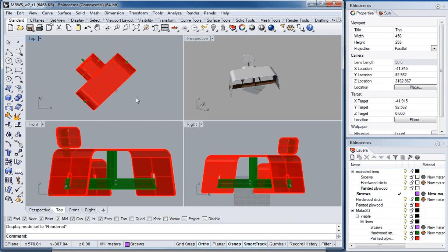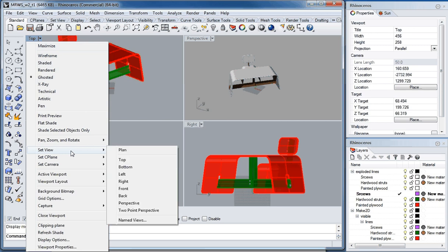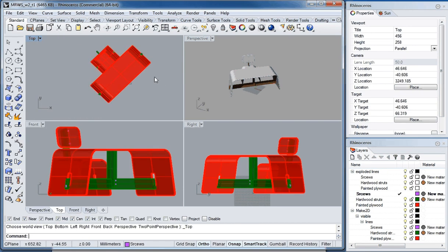So we'll just do that in here. Now what I'm doing here is I'm just holding down Shift and Control to spin around. You don't have to do that though, you can keep drawing at top. So what we're going to do is start by drawing a plane or a rectangle that is going to become our construction plane, or what we want to be seeing things perpendicular to.